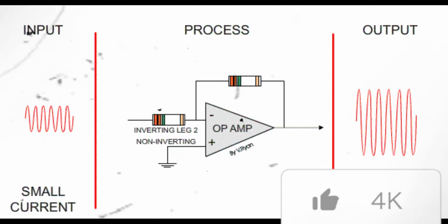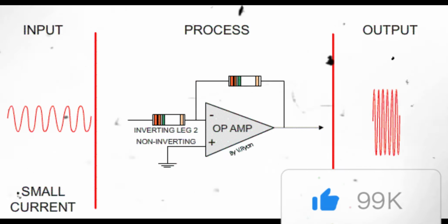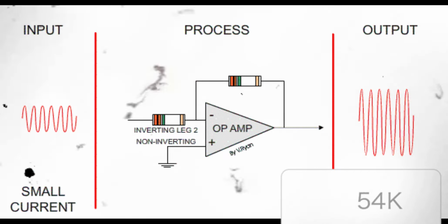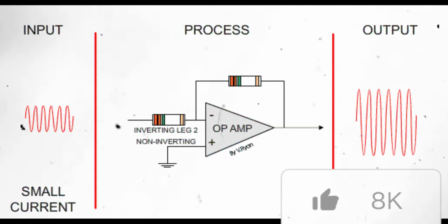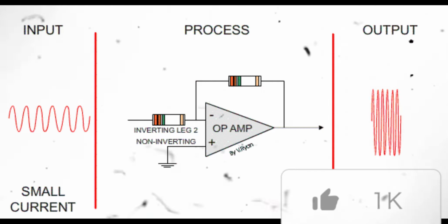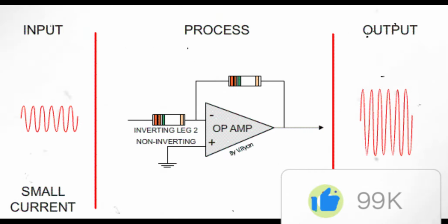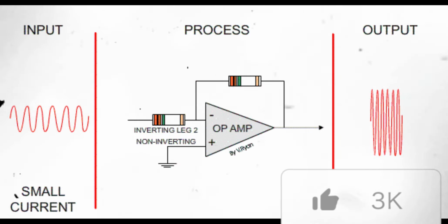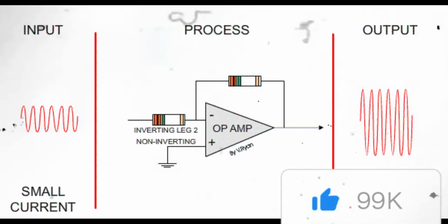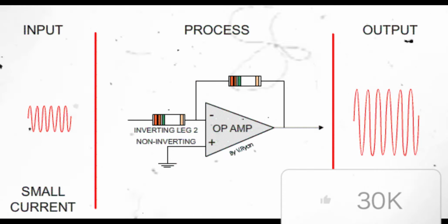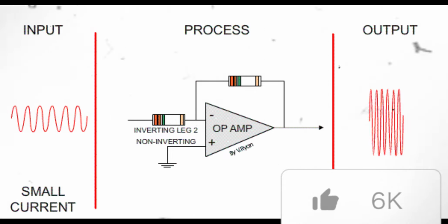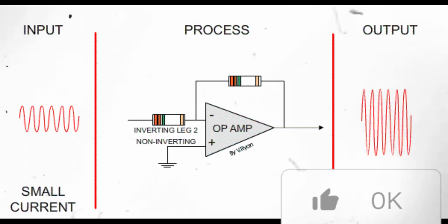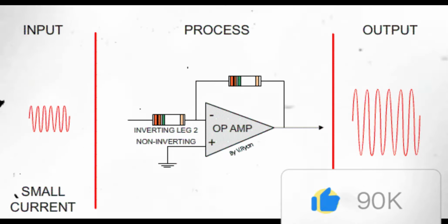An open loop gain measures a device's gain without positive or negative feedback. When listed, the open loop gain represents the maximum AC gain at very low frequencies. Ideally, an op amp's gain should be infinite, but real values usually range from 20,000 to 200,000.